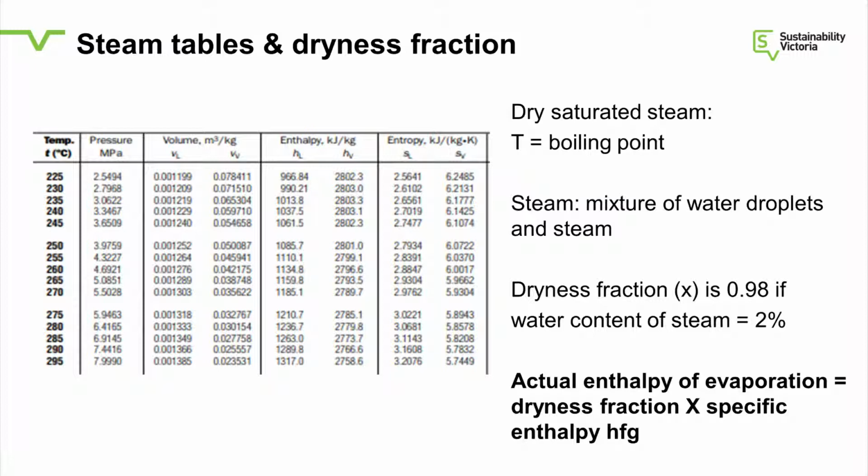The other thing is dryness fraction. The steam tables assume that there's no water carryover at all, no liquid carryover. It's 100% dry steam. In real systems, they never are. They might be 98 or 97% dryness. So that reduces the amount of energy content in the steam by that percentage.